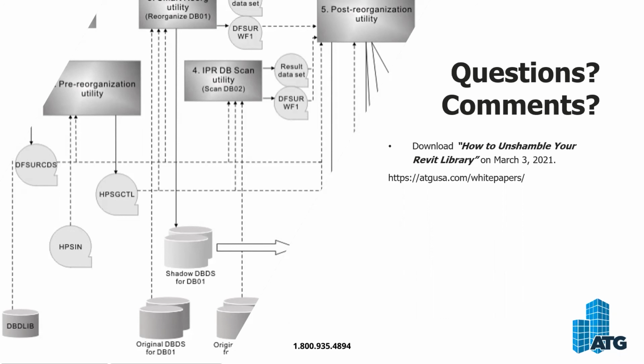That is not a curated family. That is a family that's been jammed. That's why they call it parameter jammer. It's just simply done one act of curation of making sure it will schedule with those shared parameters. There's obviously, and you guys probably know Revit pretty well, a lot of work that should go into curation even beyond that. So don't just turn your users loose to grab content and sort of fix it. You guys need to have a really good QA/QC process.